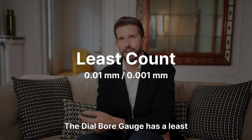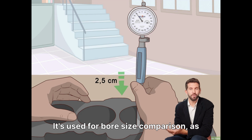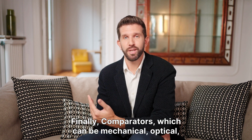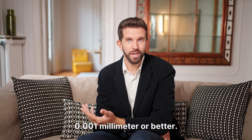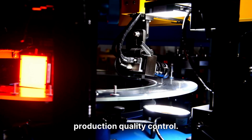The dial bore gauge has a least count of 0.01 millimeter or 0.001 millimeter. It's used for bore size comparison, as well as taper and ovality checking. Finally, comparators, which can be mechanical, optical, or pneumatic, boast a least count of 0.001 millimeter or better. Comparators are crucial for mass inspection and production quality control.